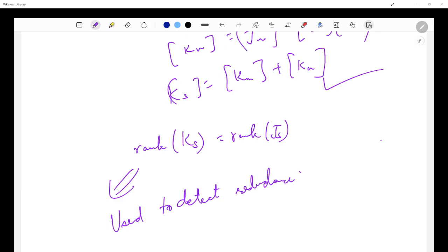Okay. So Grubler formula fails for over constrained systems, right? And the constrained Jacobian gives the correct degrees of freedom. So it helps to detect redundant links and joints. It enables kinematic and dynamic analysis, and it is very helpful in deployable structure. Okay.